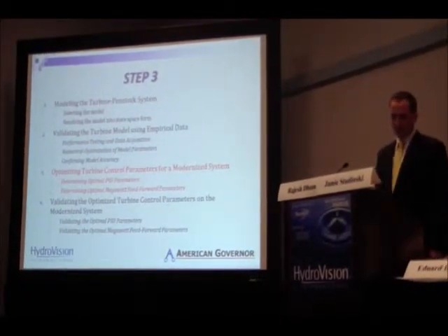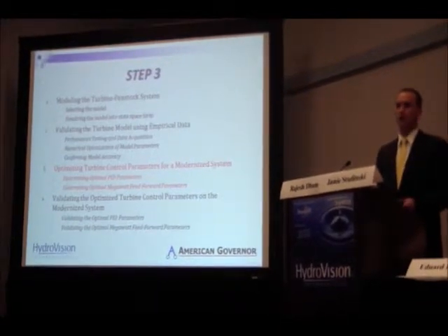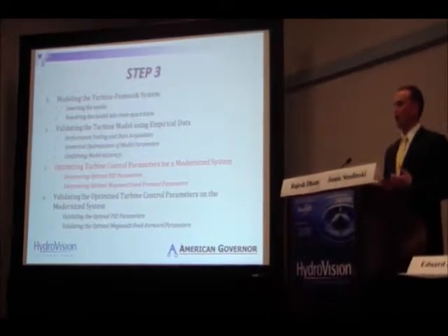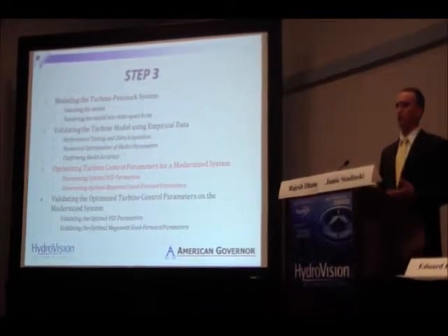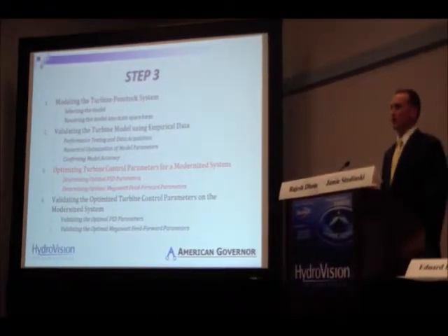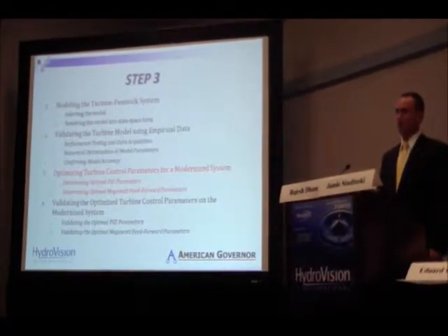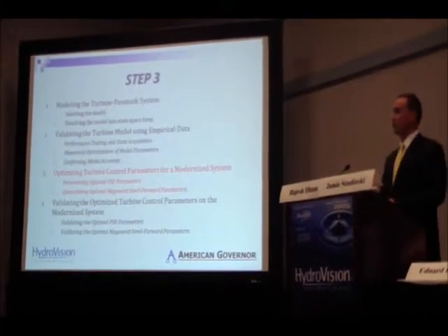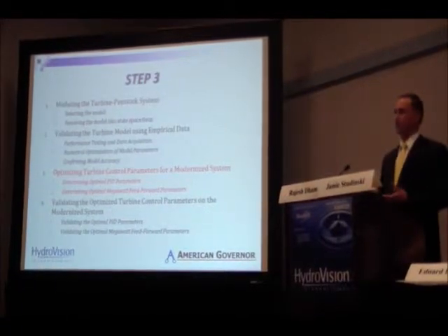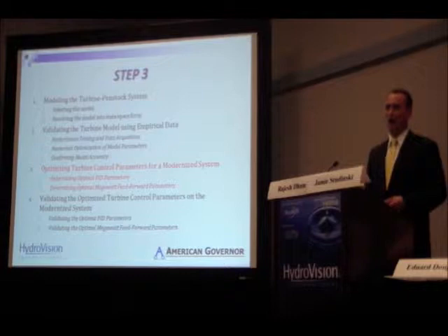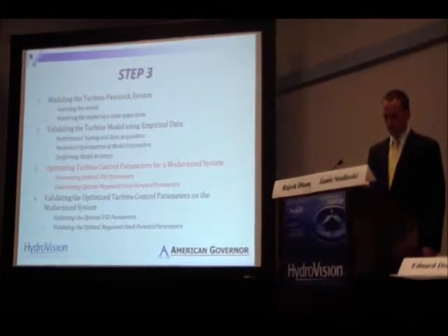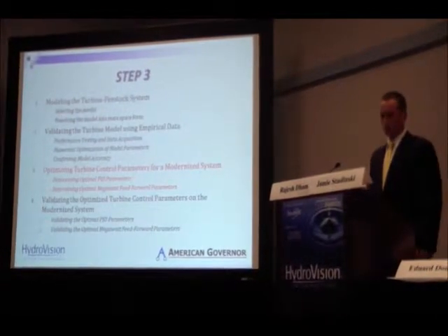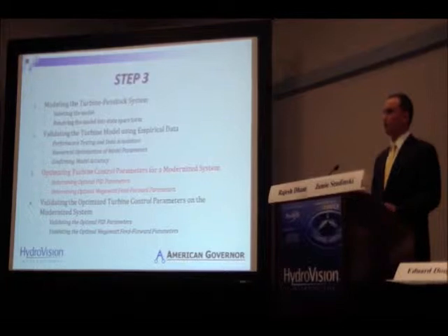So what's pretty cool is after we have this model, and what the real application of all of this can be, is that we now have something that we can test on. We can take this model and put it through the ringer. We can give it step changes. As the governor guys, we're concerned with speed stability. We're concerned with how you can load the units. And in this case, we can sit in our office essentially long before commissioning, long before we have to schedule major outages or deal with any of those considerations, and play around with the system and tune those PID parameters and our underlying control parameters ahead of time. And additionally, when we're online, we have some methods of primary power control, which we also could tune in and see how it conforms.